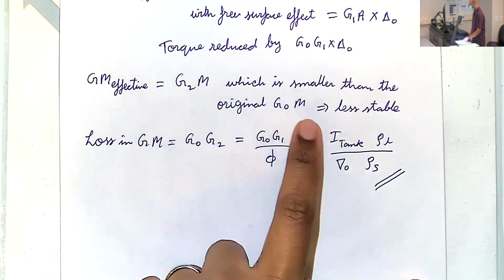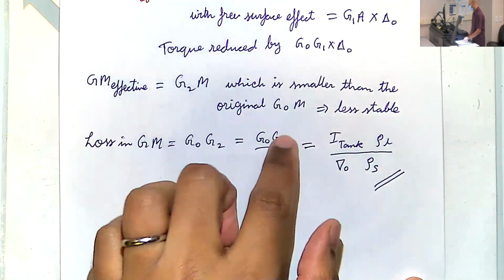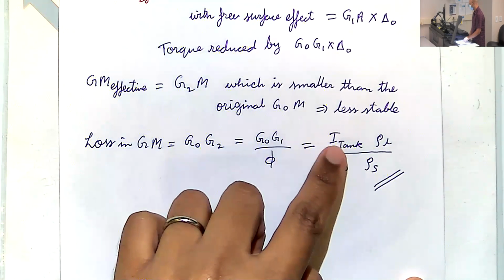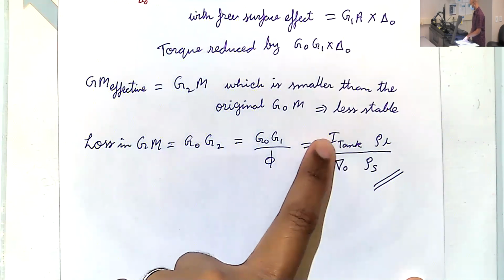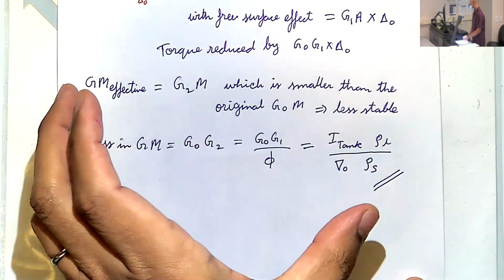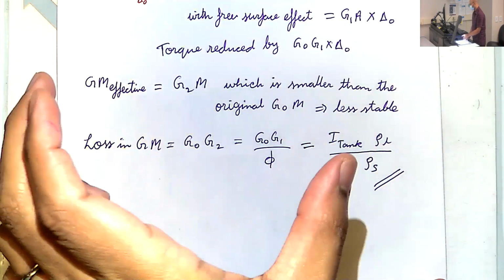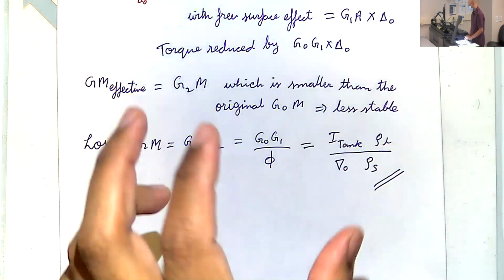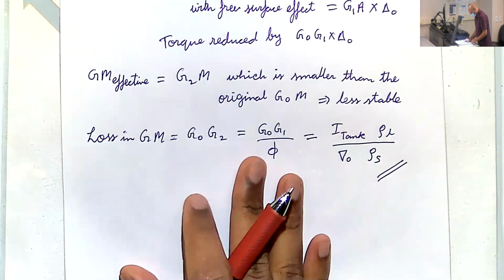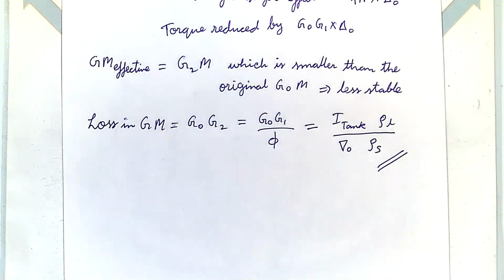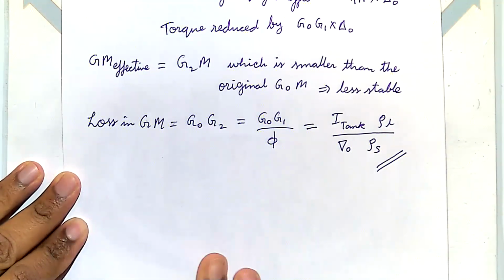Similarly, if you make a tank that's very, very wide, it will have a very high area moment of inertia. That's also not good. So you don't want wide tanks. And intuitively, it makes sense, right? If you have a wide tank, the sloshing becomes more extreme. So both these things should be avoided. That's why most tanks you see are circular.